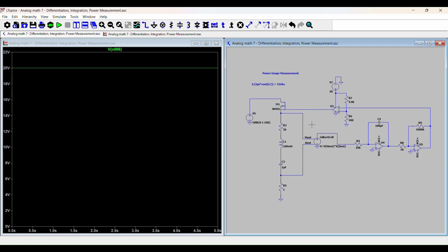When I was designing this, I was a little bit surprised that something like this can work because if we integrate the power over time across something like a resistor with a sinusoidal voltage input, isn't that going to be zero? Because the voltage swings from positive to negative, and so does the current. But actually, no. The integral of the power over time for just a resistor is always positive because the voltage is always in phase with the current. So you get a positive times positive or a negative times negative, which equals a positive sum.